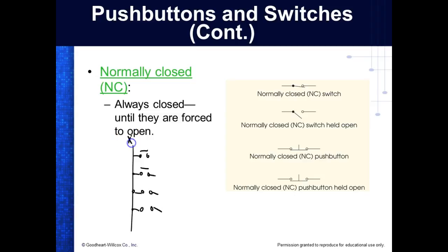So if this right here is plus, then what's the common for the switches? Plus. Well, what's this thing looking for? Negative. It's looking for a negative. We've got to complete the circuit. So if this is input 0, then this side of the PLC is going to be connected to minus. So all my ports are using minus.